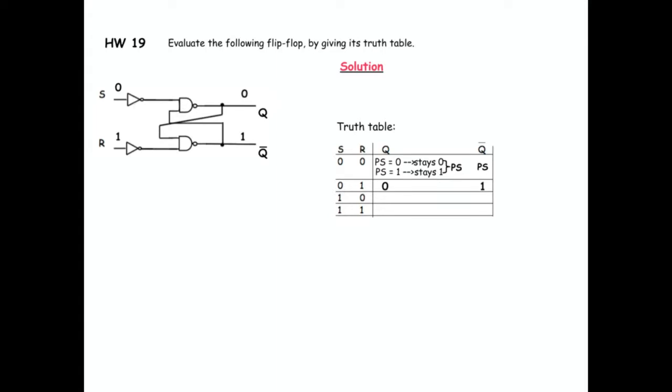And then, after that, in the next cycle, we're going to set it to 1, right? So we're going to send the 1 signal to S, and of course, we're not sending anything to R, right? We don't want to send conflicting signals. So if S is 1, inverted 1 is 0, the 0 goes into the AND. No matter what else goes into it, the AND is 0. Flipped 0 is 1. So the bit is set to 1.